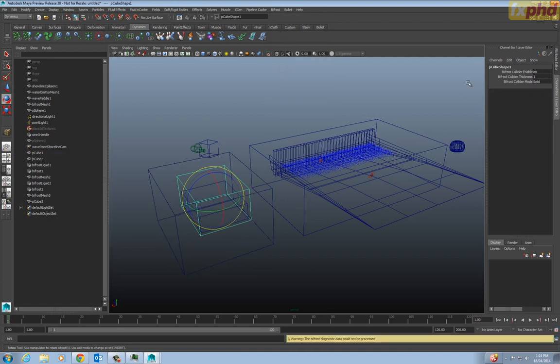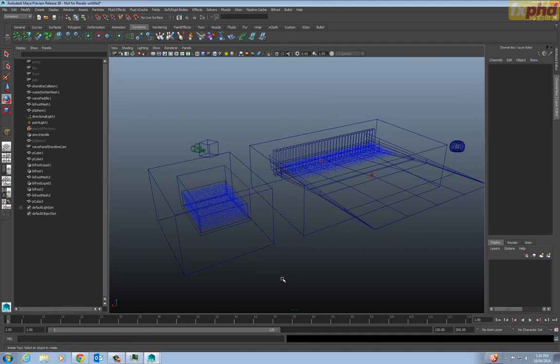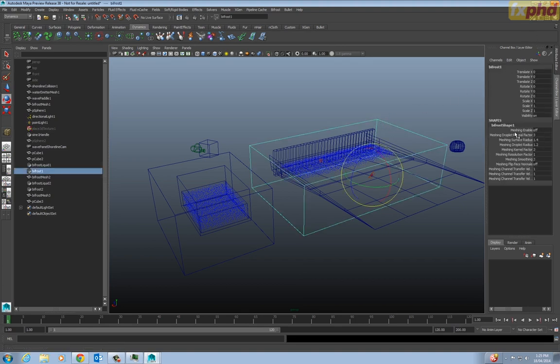And then we're going to add the container as a collider. Without the container being a collider, we have to set that to shell so that it doesn't explode the water out of it. The container must be a collider so that it can hold the fluid. You can't just have a fluid emitter that has no container to hold the water inside it.